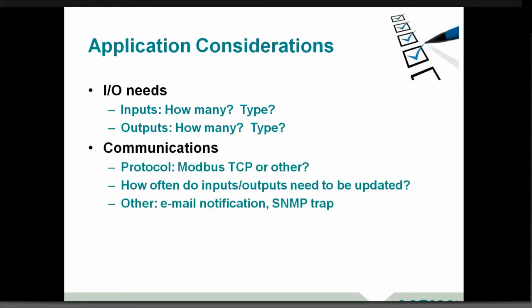Likewise for your communications. Now, just for our purposes today and not having a lot of time to get into lots of detail, what is your communication protocol you'd like to use? We certainly like to endorse open standards that allow you to do best of breed solutions to be able to bring things together very quickly. And I really like Modbus TCP because it's simple. There's lots of compatibility with cross-vendor solutions, and it's easy to implement. So that's certainly one of them. But by no means is it the only solution to use for this.